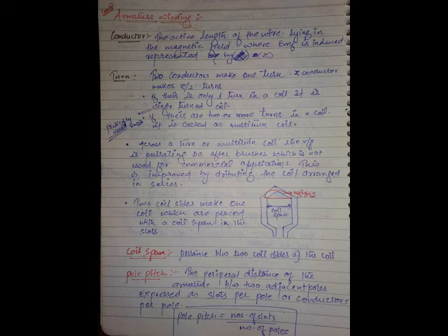Now, let us think there are four poles. Same 360 degrees mechanical rotation. When a conductor makes a 360 degrees mechanical rotation, under one north pole you will have one cycle, under south pole you will have one cycle. This is known as one electrical cycle, and this is known as another electrical cycle.